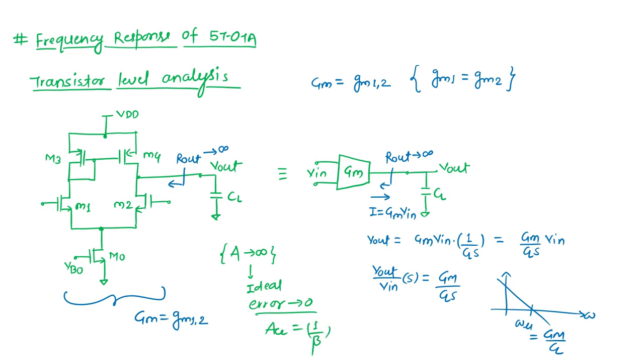Okay, so now I will specifically discuss this 5 transistor OTA structure, and we will see how to calculate different poles and zeros in the non-ideal case. Okay, so let us see. So what we know is that practically we don't have infinite output impedance for this 5 transistor structure or this GM cell. Now we'll see exactly where the poles and zeros are in this structure.